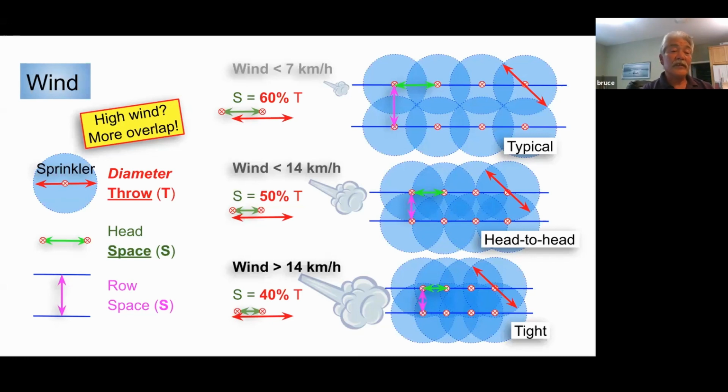One thing that obviously is important is when you're laying your sprinklers out on a given field, be cognizant of the wind. There's always going to be wind in some circumstances, but if the wind is typically coming from a given direction, and it can be fairly strong at specific times of the year when you're irrigating, you may want a stronger spacing in those areas, because the wind is going to be blowing the sprinklers' water further. Let's say we were looking at an average spacing of 50 feet.